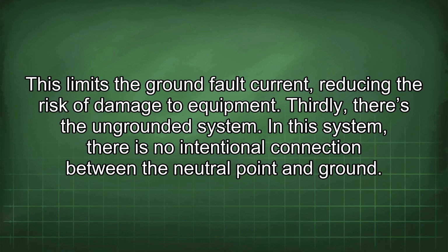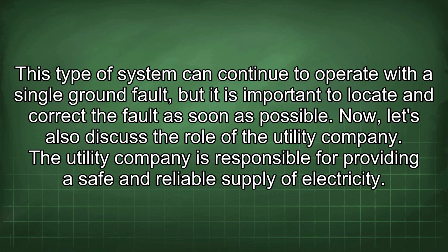Thirdly, there's the ungrounded system. In this system, there is no intentional connection between the neutral point and ground. This type of system can continue to operate with a single ground fault, but it is important to locate and correct the fault as soon as possible.